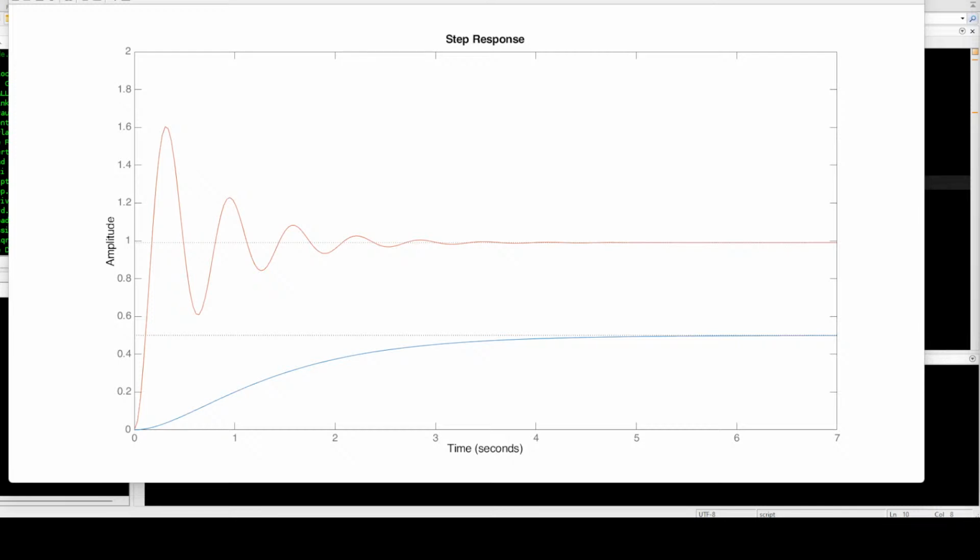Okay, Cohen-Coon. Perform an open loop test of the model. Measure the process in steady state. Okay, no, we don't want this one. Determine the sign of the process gain. Open loop. Implement a proportional control and set a new set point. Increase proportional gain until it's sustained periodic. No, we don't have sustained periodic. Okay, closed loop on-off test. Let the process settle into a steady state. Move the set point from the current steady state. Implement an on-off relay controller. Man, these are all weird.